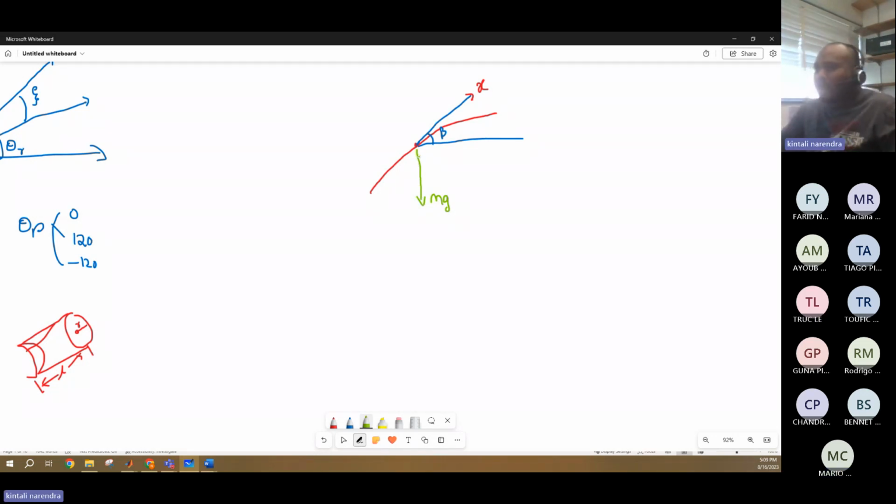So what other forces can you imagine when your vehicle is moving? Whether it is an electric vehicle or a gasoline vehicle, you have one force called tractive force, FTR, with which your vehicle will start moving, and this is the force because of the motor in a vehicle. Now, when the vehicle is moving forward, there are a few other forces acting against the vehicle. One is aerodynamic force.